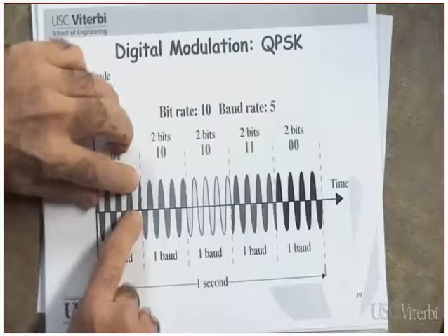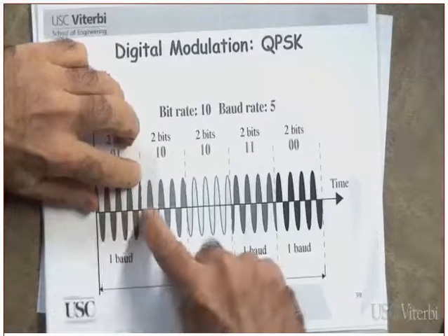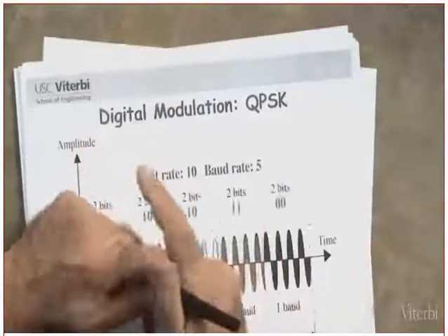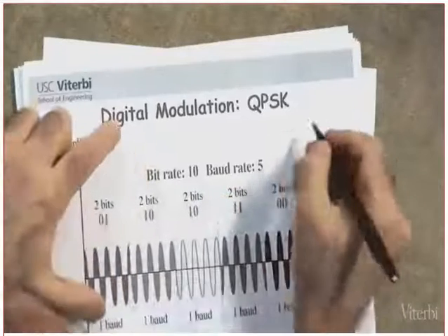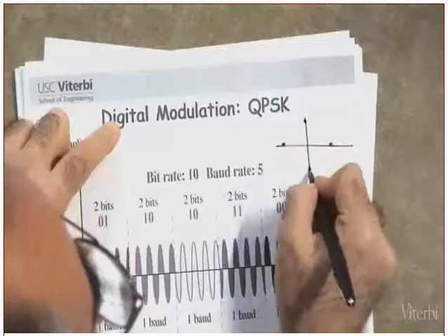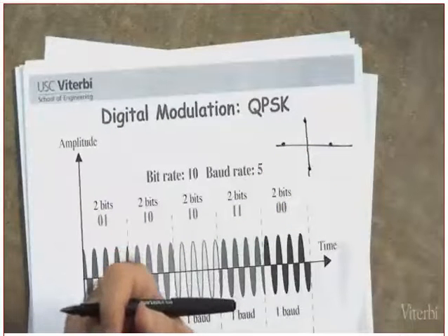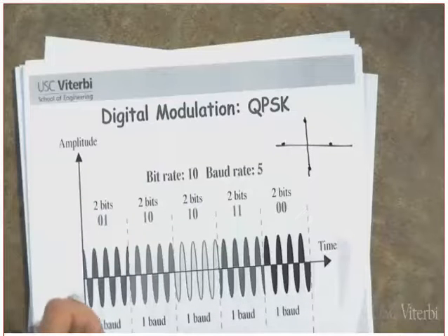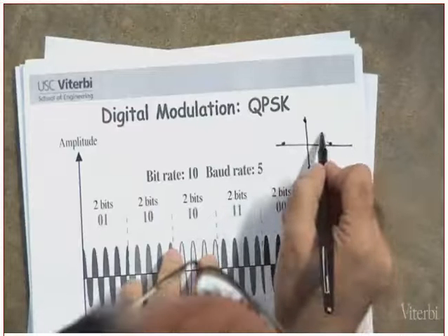Let's see what happens at the boundary. What does the amplitude go from where to where? From positive to 0. Did you understand that or not? By the way, have you studied constellation diagrams? Yes. Signal constellation? Can you show it to me for the QPSK? How does it look like? Circle. One here, 4 phases. Question, are they on a circle? Why are they on a circle? Because the amplitude is constant. But you would say, Professor, you just said the amplitude is not constant. Make up your mind. At the transition from one symbol, where are these? These are on a circle.